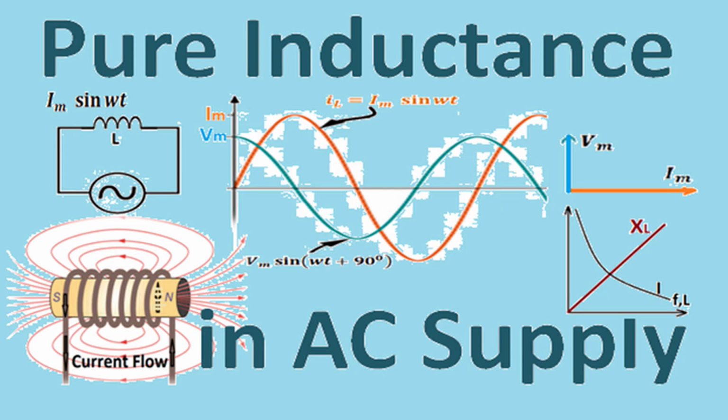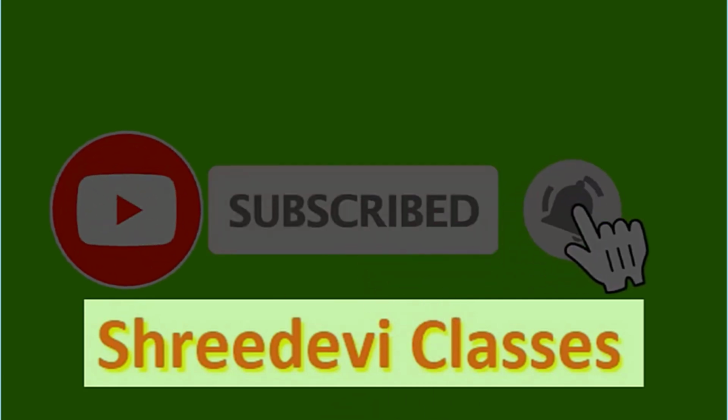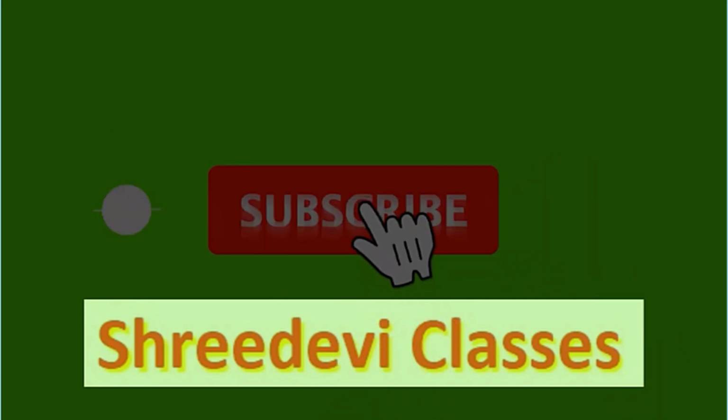In this process, when current rises the inductor stores energy, and when current decreases the inductor releases the same stored energy of the magnetic field, and average power consumption by such a circuit in alternating supply is zero, and such power is known as reactive power.